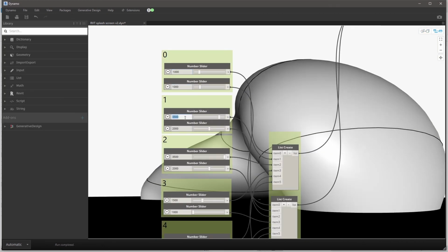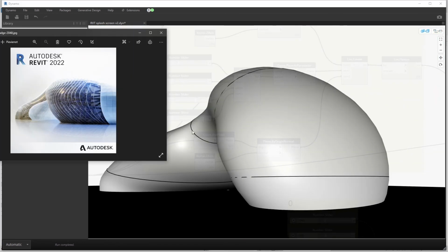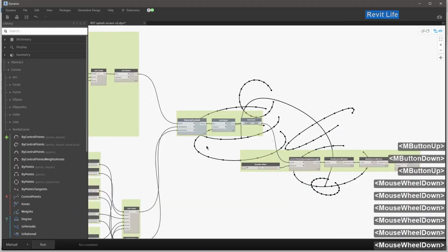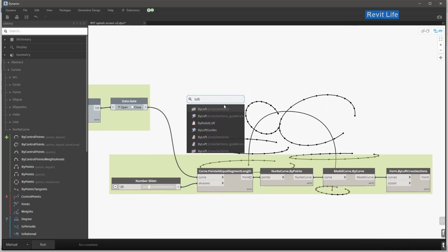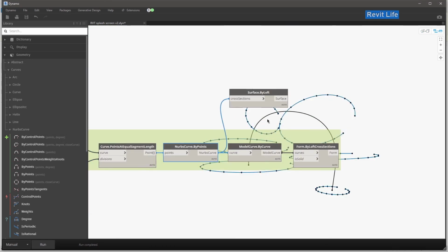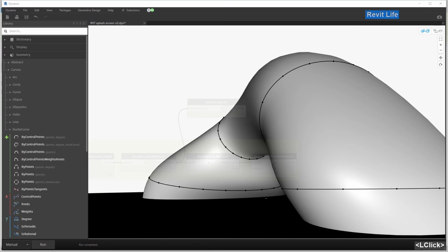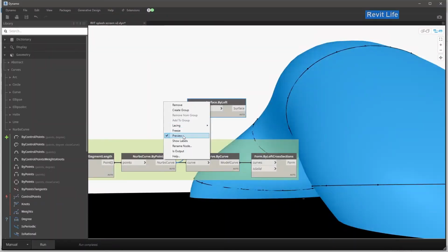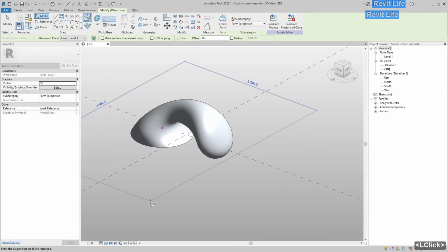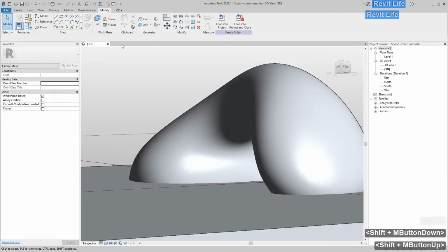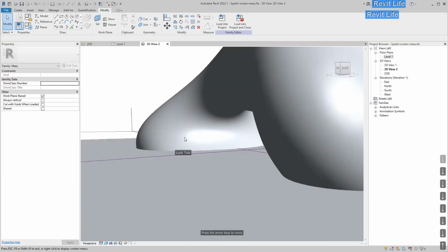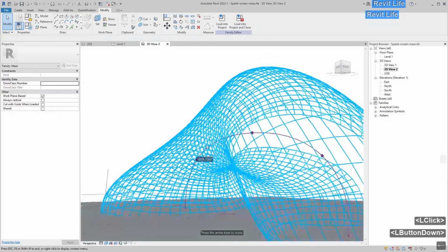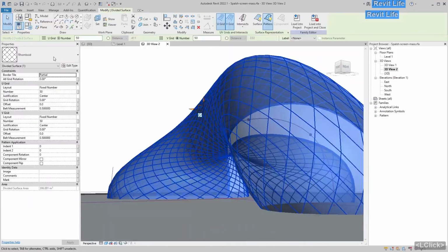So the next big problem was when I tried to push the surface into the Revit mass surface using form by loft cross sections. It just wouldn't push the surface into the Revit mass family. So what I had to do, I had to retrace those ellipses so that the cross sections aren't made out of continuous ellipses, but are made out of splines that have a beginning and an end point. So it's not a continuous surface.